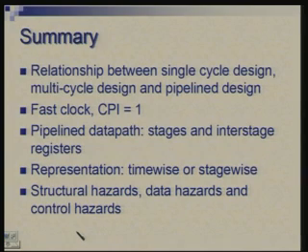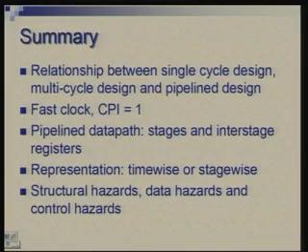Okay, so I have discussed the basic ideas of a pipeline design. We began by looking at the relationship between a single cycle design and multi-cycle design, and then bringing pipeline design into the same framework and seeing how they compare in terms of clock period and CPI. So, we have seen that the pipelining approach gives you a fast clock similar to multi-cycle design and low CPI similar to single cycle design.